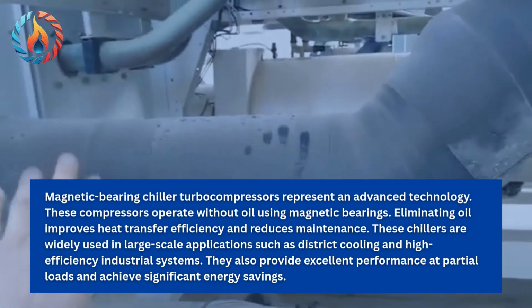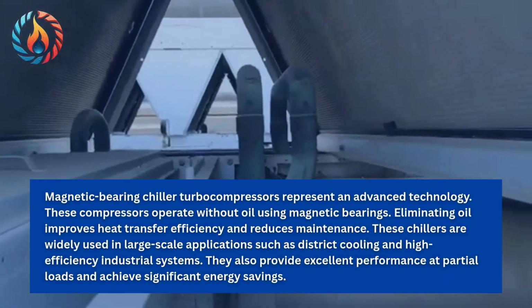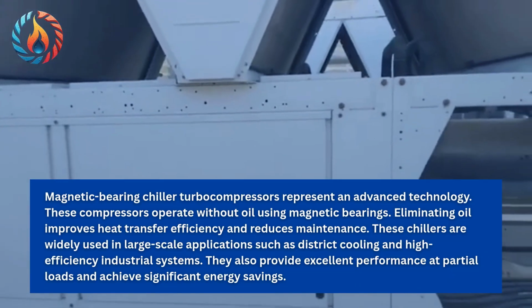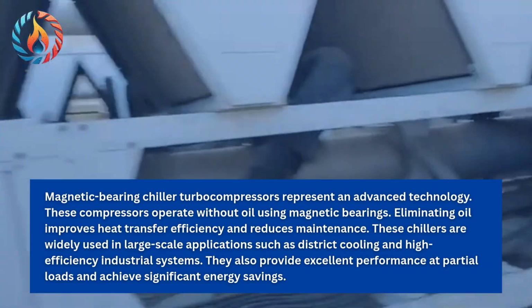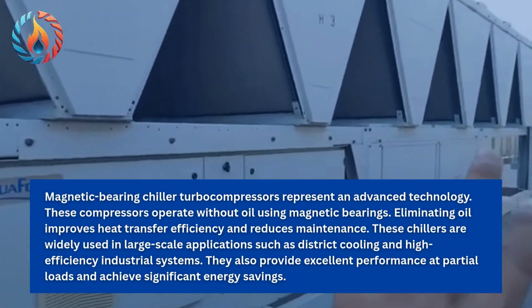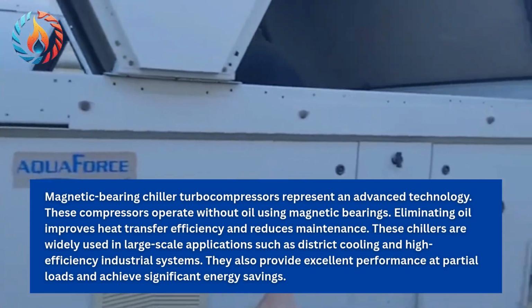Magnetic bearing chiller turbocompressors represent an advanced technology. These compressors operate without oil, using magnetic bearings. Eliminating oil improves heat transfer efficiency and reduces maintenance. These chillers are widely used in large-scale applications, such as district cooling and high-efficiency industrial systems. They also provide excellent performance at partial loads and achieve significant energy savings.